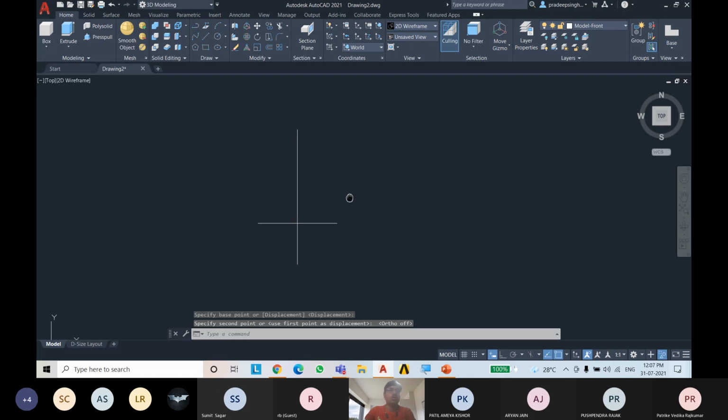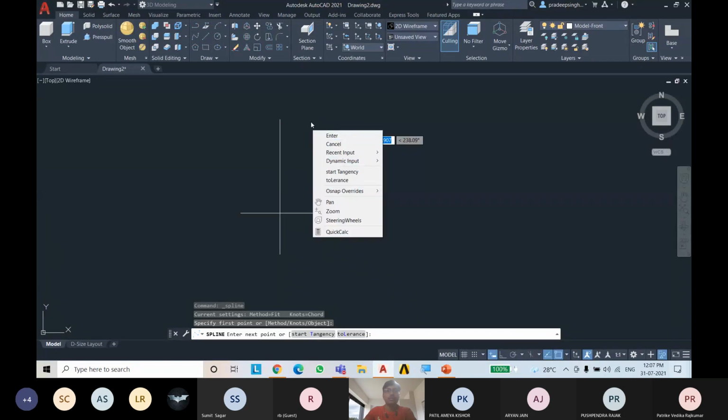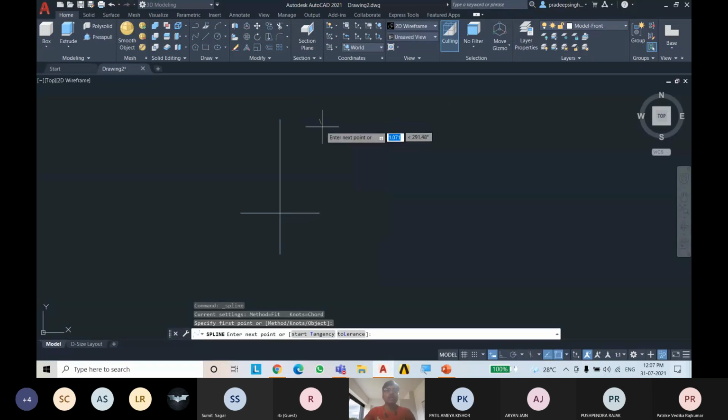Now we will use polylines. The difference between line and polyline is that all the polyline segments are connected. Use the polyline, go there, don't click, and extend it, then click on the connecting lines. Then right click on these connecting lines.